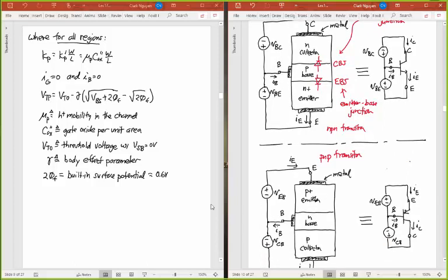And these junctions, again, I can define, and I can define diodes here, but now the diodes for this are going the opposite direction to the diodes up above. Now the diodes are sort of facing each other inwards here. And now I've drawn the emitter base junction above. And so you can see the symbol for this transistor.